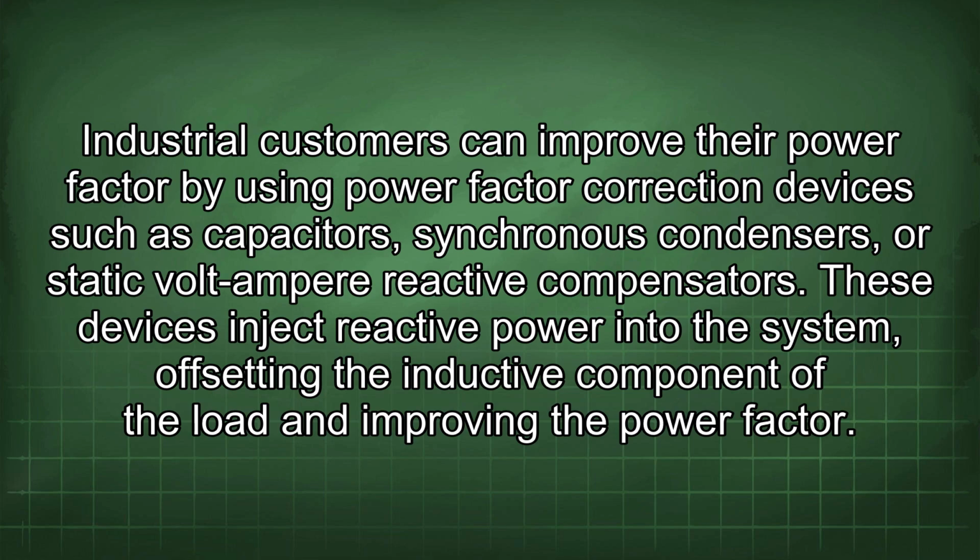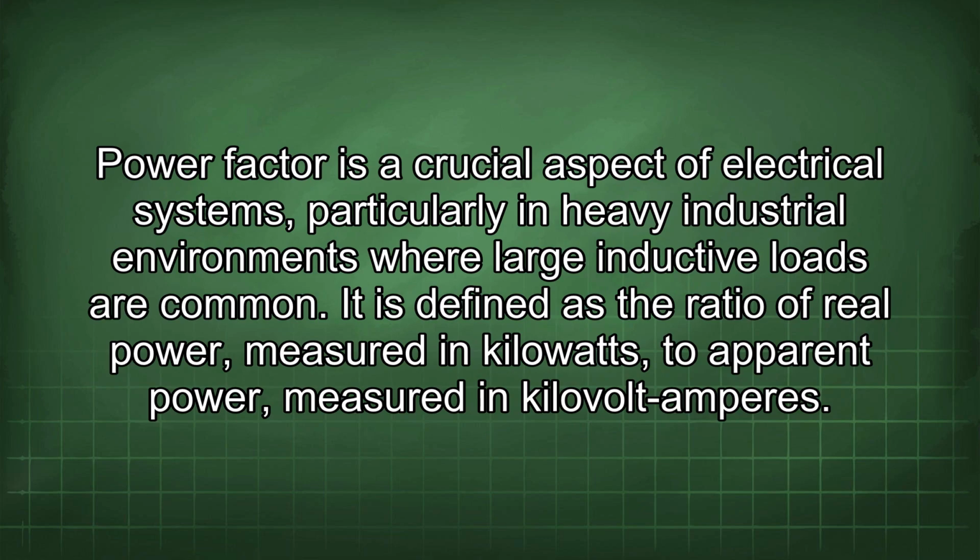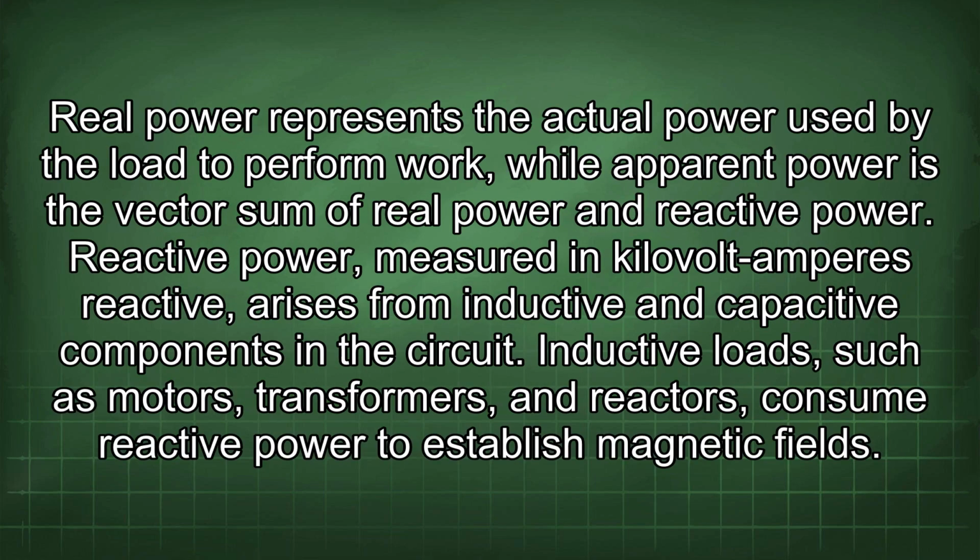Power factor is a crucial aspect of electrical systems, particularly in heavy industrial environments where large inductive loads are common. It is defined as the ratio of real power, measured in kilowatts, to apparent power, measured in kilovolt amperes. Real power represents the actual power used by the load to perform work, while apparent power is the vector sum of real power and reactive power.